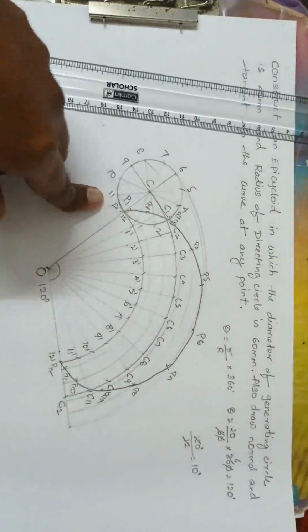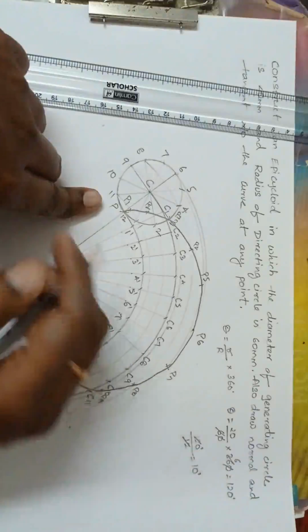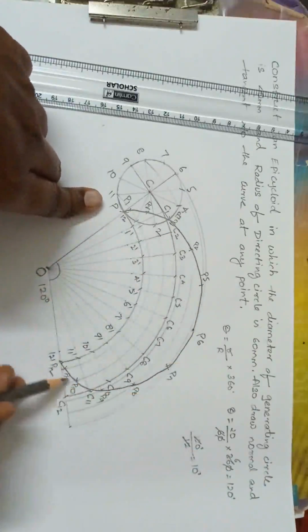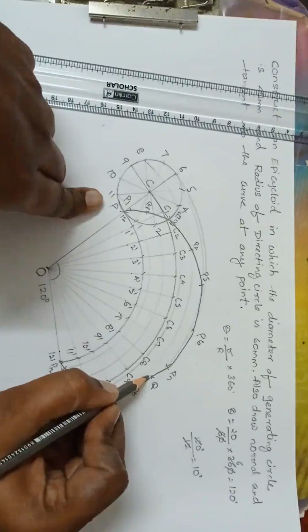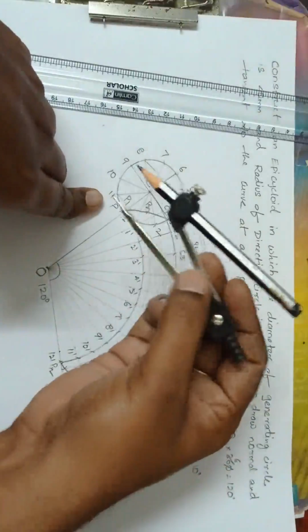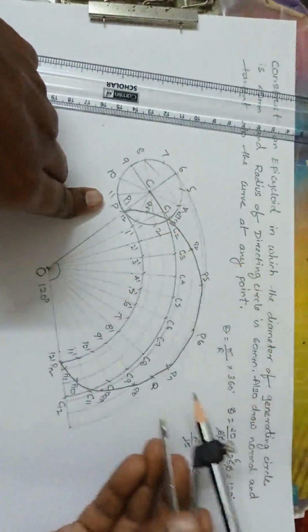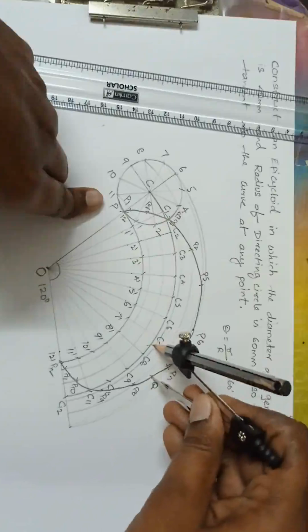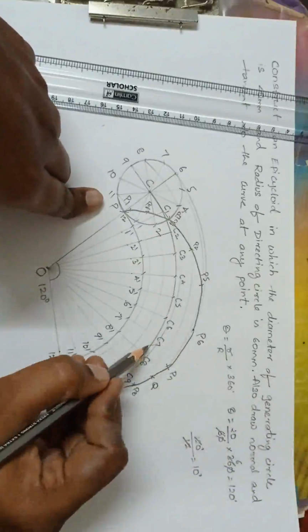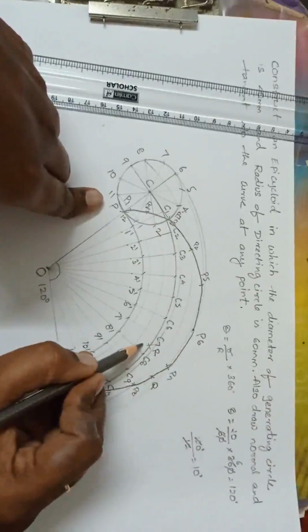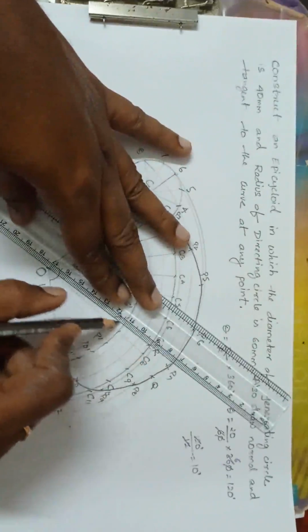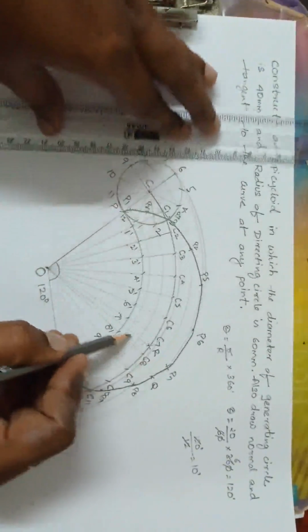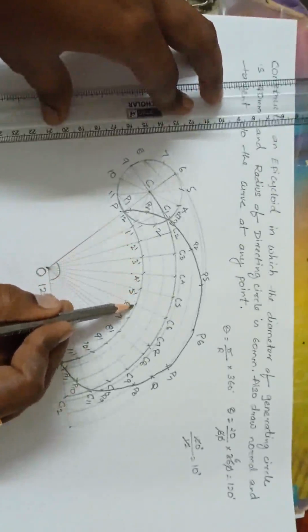Okay, fine. Now how to draw the normal and tangent? Mark any point on this curve, on the epicycloid. I'll call it Q. Somewhere I'm marking. Okay, now take the radius of the circle. Q as center, cut the center line somewhere. Now I'm calling this point R. Now join R and O very lightly. This line will touch this bottom curve. I'll name this N.